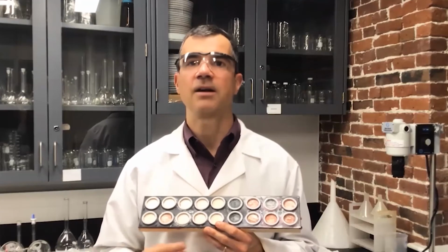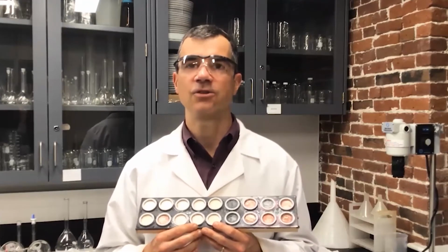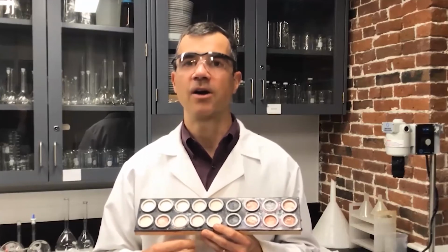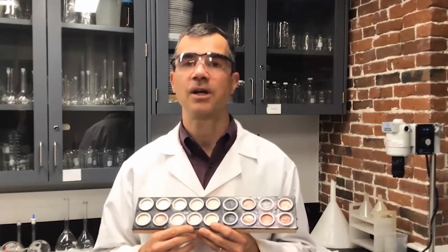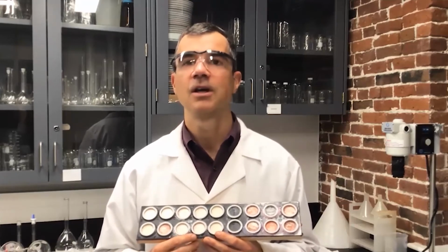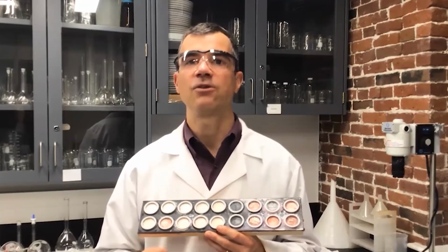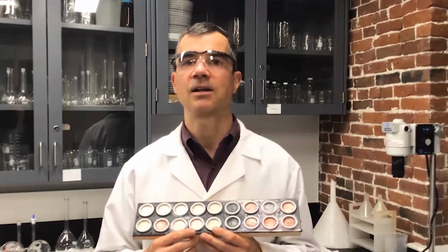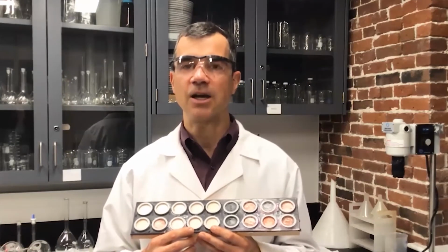So we took that industry standard specification and we modified it. So what we did was we required a primer layer to be added to the substrate, and we increased the top coat layers from 3 layers to 4 layers. And we also tried to make better adherence between the coating layers. So we had sanding and cleaning steps between each layer application.